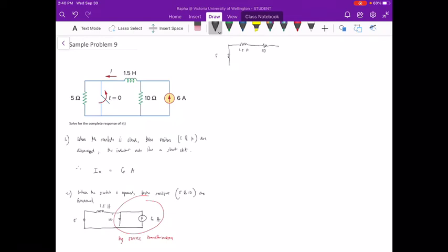The entire circuit rather becomes a series circuit. Then our voltage source is simply equal to current times resistor. So we have 6 A times 10 ohms, we have 60 volts. So we obtained that by source transformation, which we have learned from the previous lesson.